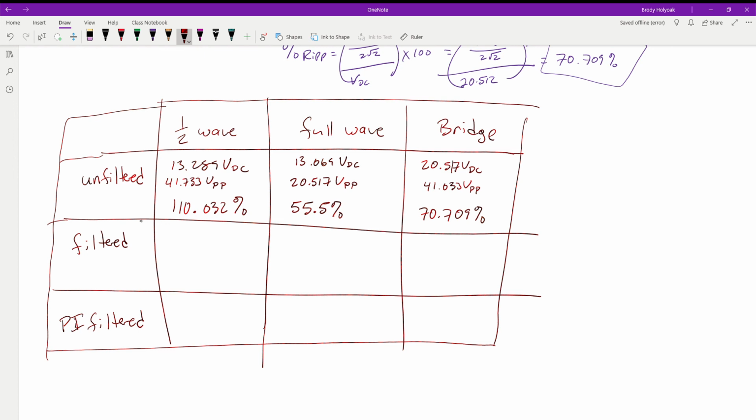So this is the big thing here. This is the big avenue here, is we get a higher voltage out than any of these guys. The difference between the half wave and the full wave is we're able to cut the ripple in half by doing it this way. We lost a little bit of our max voltage, but the trade-off is there. Maybe we have a little bit less design that we can do with that, but it gives us the ability to have a tighter signal.